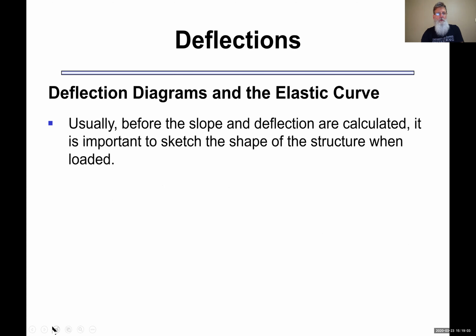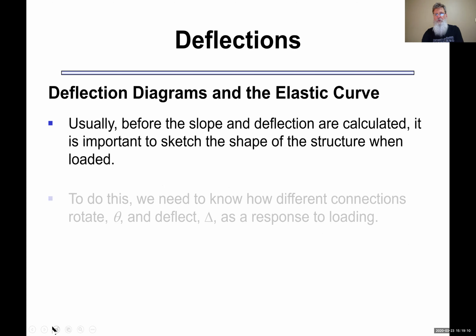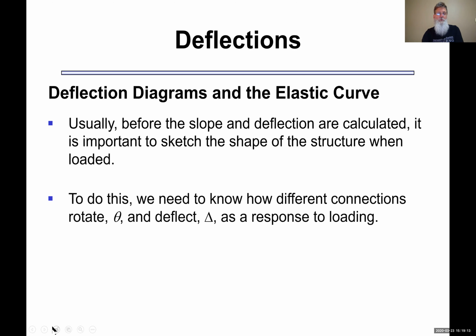So before we can talk about deflection, we usually talk about slope and displacement. It's probably a good idea to see how those things will behave. So typically we use this notation. You can see here the theta is a typical notation for rotation or slope, and that's going to be the slope of the deflected curve. So if you can write an equation for the deflected curve and take the derivative, then you would have the slope, theta. And then there's a lot of different symbols used for displacement.